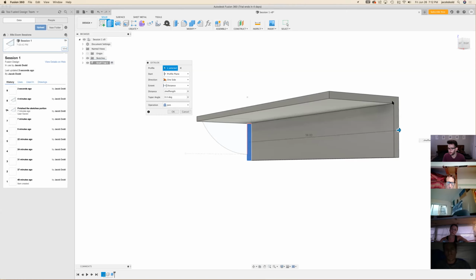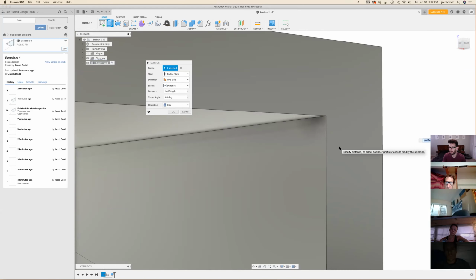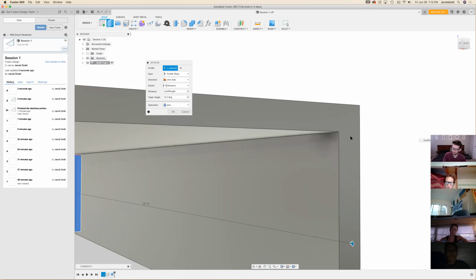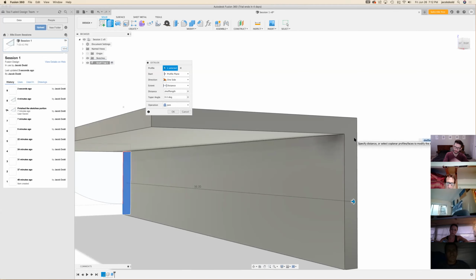But you can see, if you look in this corner, it's like a solid object, right? Which is not really how it would be constructed, or if that's even possible. You'd have to have a beam and then cut out this whole excess to make that solid object. So you can see here, it's because it's defaulted in the operation to join instead of making a new component or a new body. And I'm kind of hesitant to go ahead without Todd there, because this might be useful.